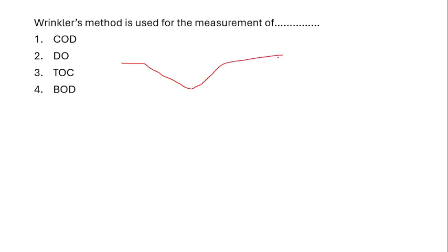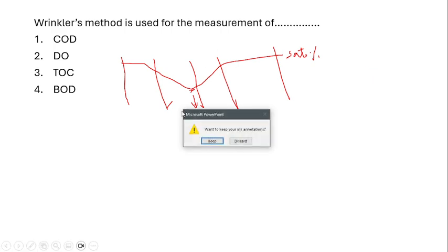In any water system, such as a river, the quality of the water is determined depending upon the concentration of dissolved oxygen. This is the critical point below which, when DO goes, no living organism can live in that type of water. So DO concentration should always be maintained near the saturation percentage. One of the best methods to estimate this DO concentration is the Winkler method.